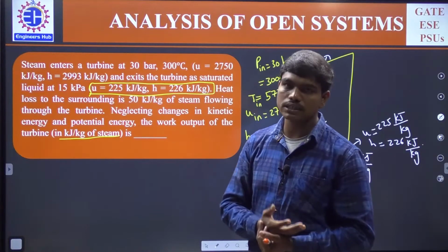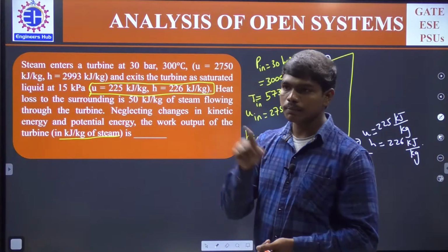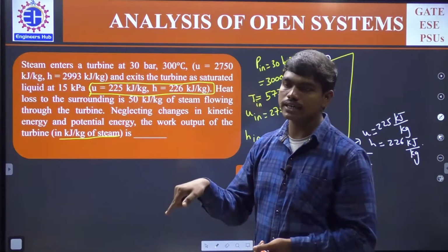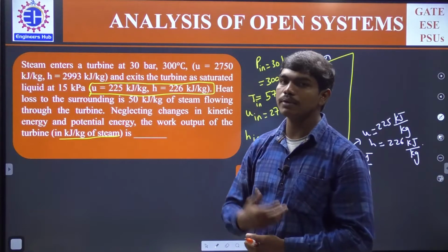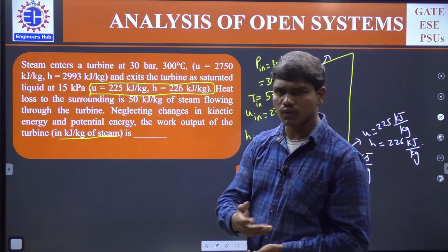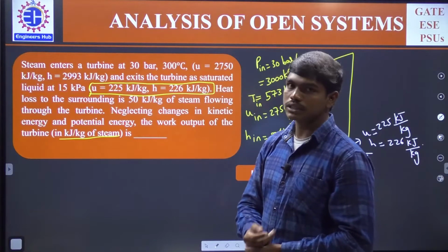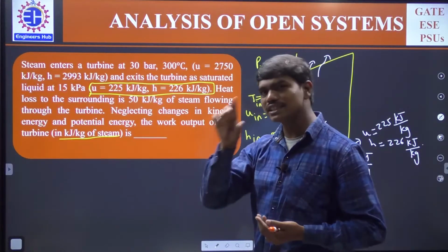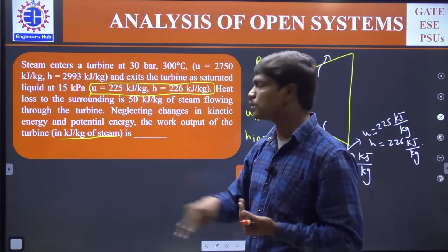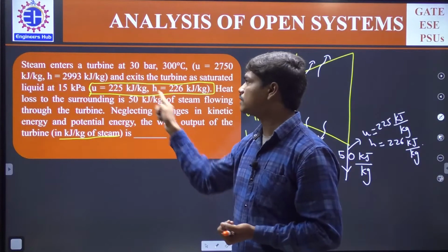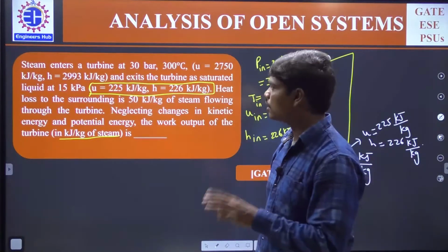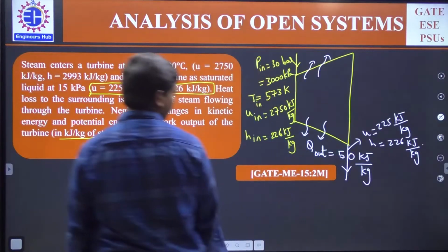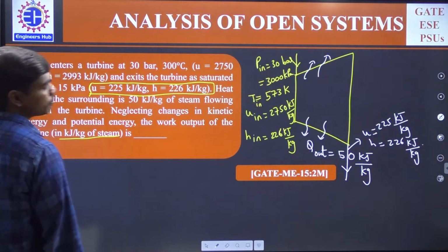For example, in power plants, in Rankine cycles, the condenser pressure where the heat is ejected will be very low compared to atmospheric pressure, like 30 or 40 kilopascals hardly. Since H is equal to U plus PV, and since P and V are both very low at this condition, U and H will be almost the same. These are some observations you could make while viewing the values. Anyhow, that's not the main point of interest at this moment.